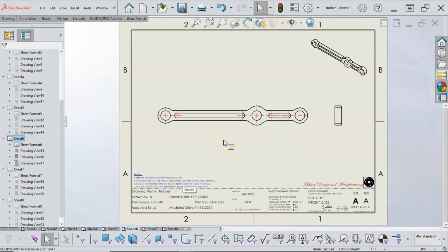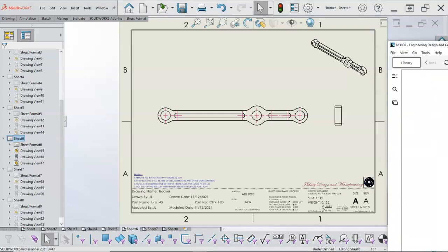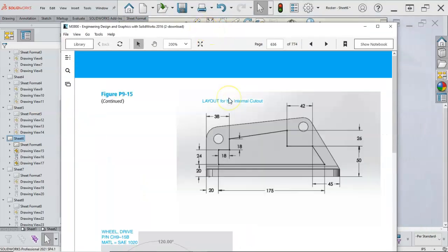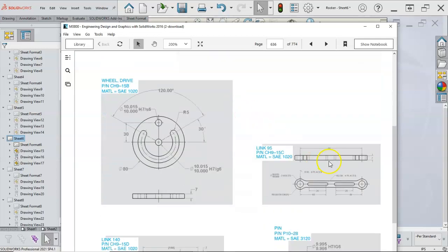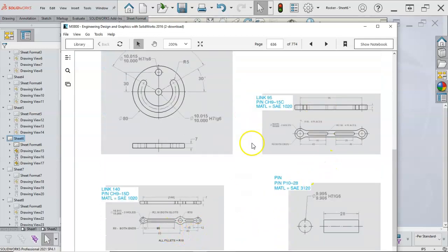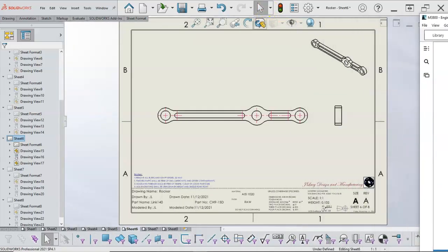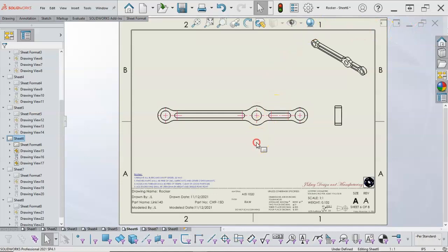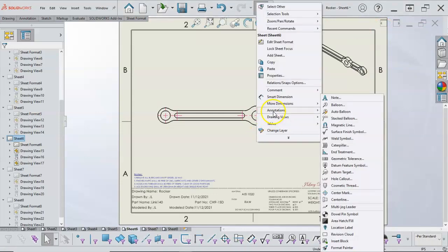All right, so this guy, since there's not really a square datum to pull from, we could stay pretty close to their dimensioning scheme. I'll fly that back in and see if we can find it here, which was pretty much between centers and lengths. Since the pivot is there, I'm kind of tempted to make that the datum, that center bore on this piece, and just pull all those dimensions from a single location.